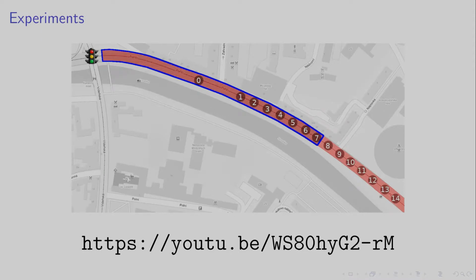You can see what the final trigger distances look like at a real intersection. The area with blue border is the polygon currently used, the virtual border I spoke about earlier. In comparison, the numbers are trigger points for our solution based on the number of vehicles in the queue. You can see that our method basically shifts the trigger distance based on the queue size.